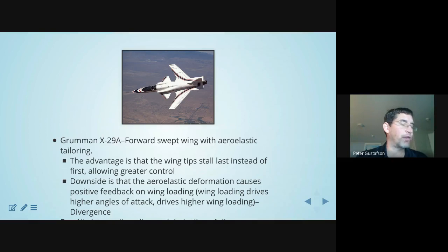I'm going to expand on Joel's answer just a little bit. The amount of relative heat transfer scales with the surface area that the airflow is over. So by putting foam in the middle, not only do you get the structural support that Joel alluded to from the foam, but you also increase the surface area that the heat can transfer convectively into the air that's flowing through it. So you get two purposes. You're double dipping there, multi-purpose, multi-function devices. Great question, thanks.